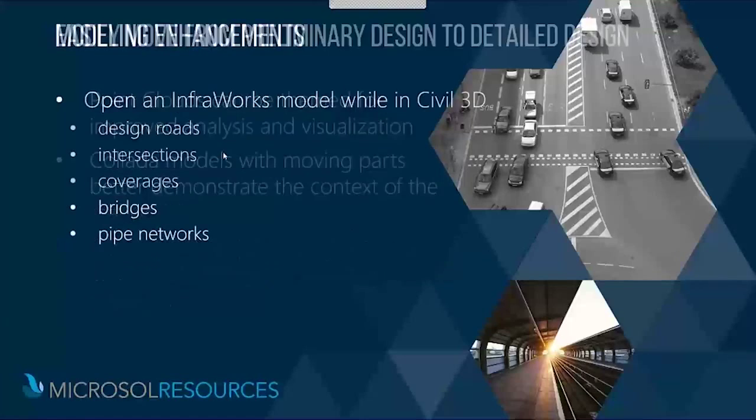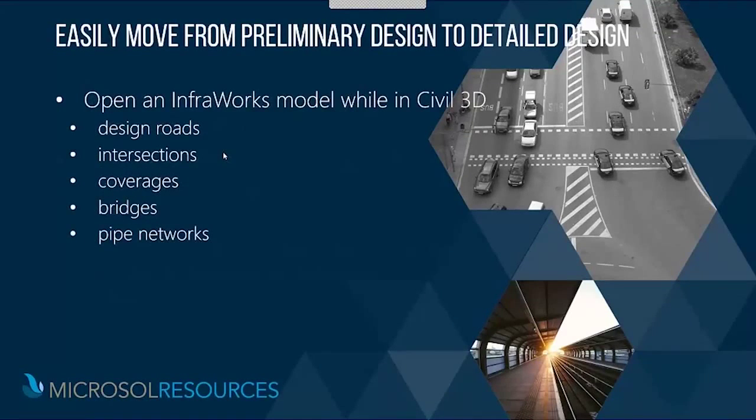All right. Now, the next group of slides really has to do with the way that Civil 3D interacts with InfraWorks. And there's been a lot of new development in the way that process works. In previous iterations, and this is more towards the civil engineering attendees, bringing information back and forth into Civil 3D was a little bit more manual, in the sense that you were using either an IMX file format or a LandXML or even just simple Civil 3D files to bring in data back and forth, and you lost a little bit of that connectivity.